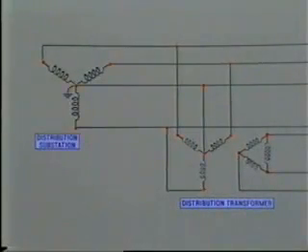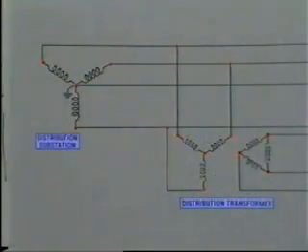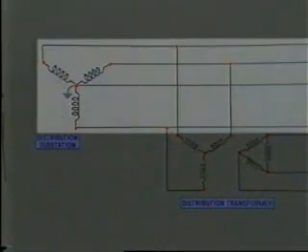This is the reason that many utility companies do not ground the primary neutral of Y-connected transformers, nor connect it to the line neutral. Remember, the primary feeder is already grounded at the neutral so as to anchor the primary system voltage.